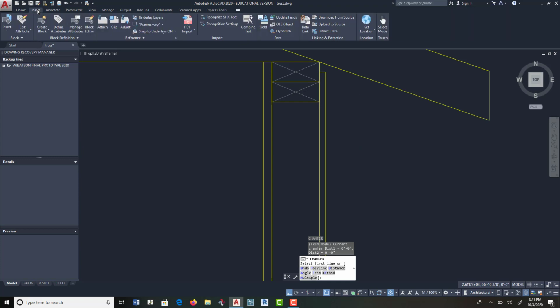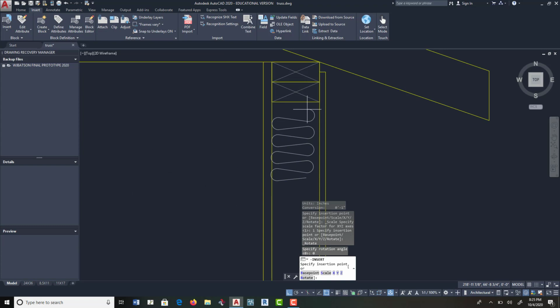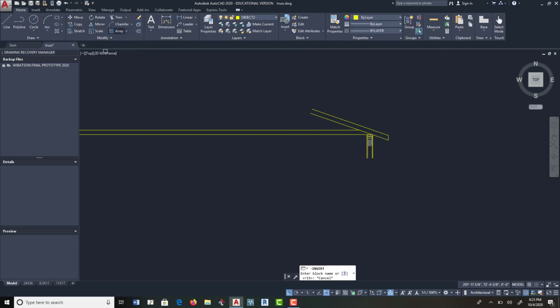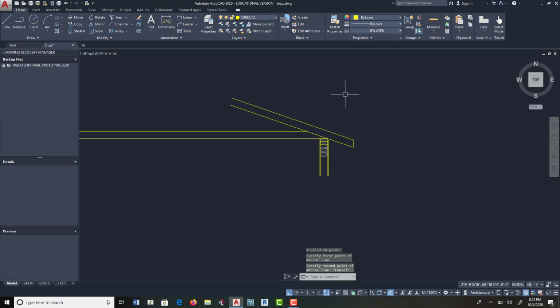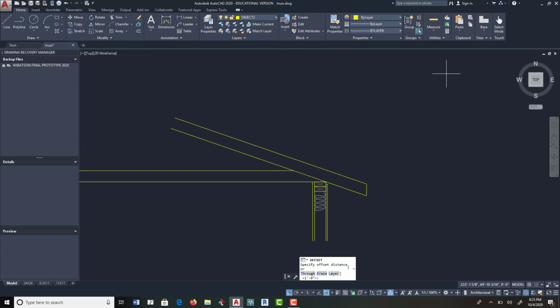And if you want to, you can put your insulation in here, because the more insulation you put in there and the more walls, the less you have to do. Because what you're going to do in the end is mirror all of this information over here when you're done with it, okay? So do as much as you can over here, and then you don't have to draw it over there. All right, and now we're going to put the sheathing on the roof, so that's going to be offset. That's 7/16 of an inch too, 7/16. Okay, and we're going to offset that.